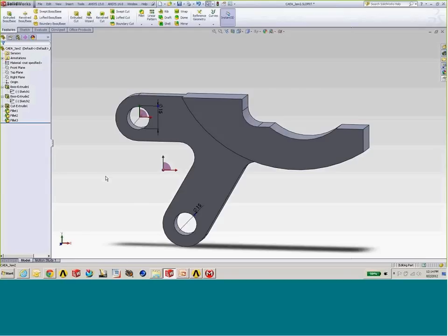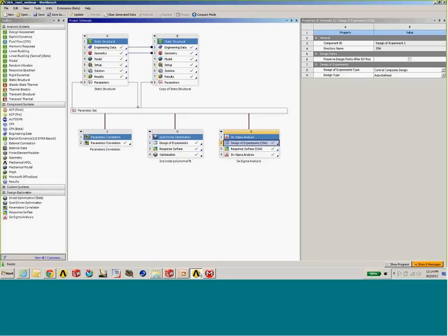So I've identified my CAD parameters, and I've identified name selections that I want to bring across. I'm going to open up the ANSYS menu by pulling down ANSYS 14 and specifying that I want to enter the Workbench environment. And we're presented with the project page, and typically what you will see is just a geometry item listed on the top, but because of the number of design points that we're going to be evaluating in this webinar, I've taken the liberty of setting up the model and generating the design point solutions for you.